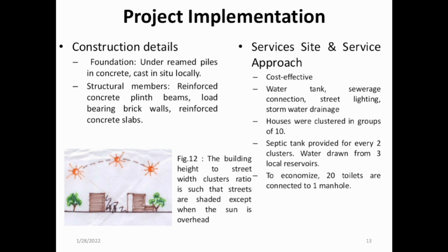Project implementation. Let's first see the construction details. Foundation: since the soil was black cotton soil, cast in situ under-reamed piles in concrete were used. Structural members used were reinforced concrete plinth beams, load-bearing brick walls, and reinforced concrete slabs.